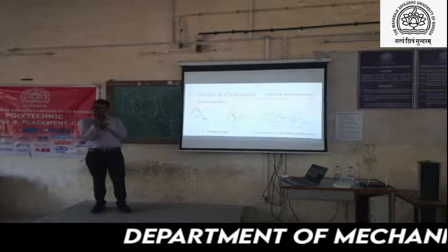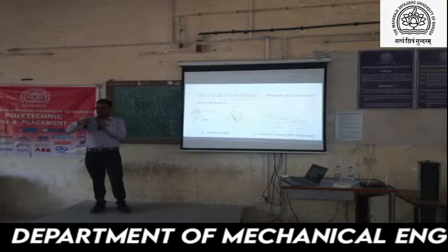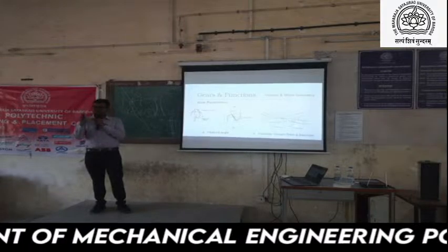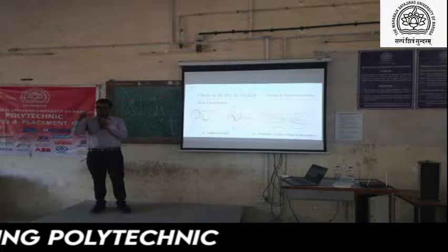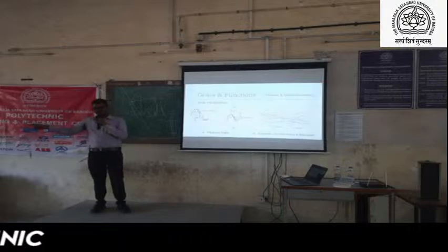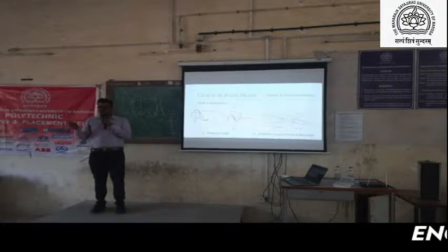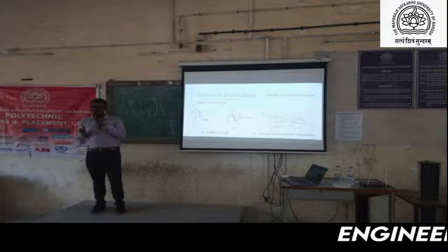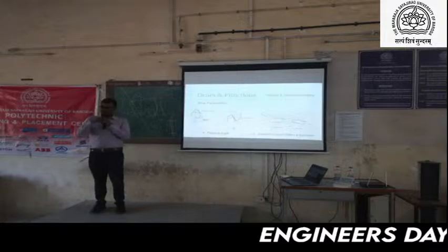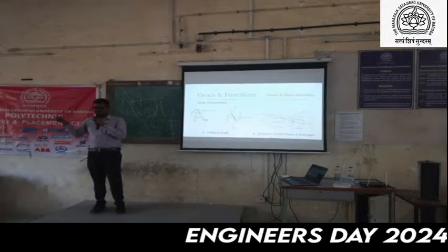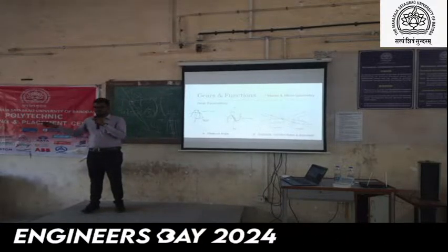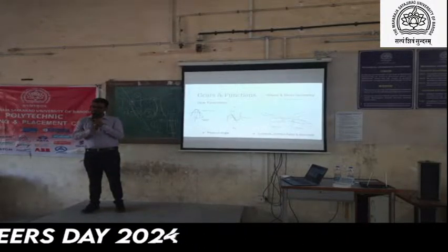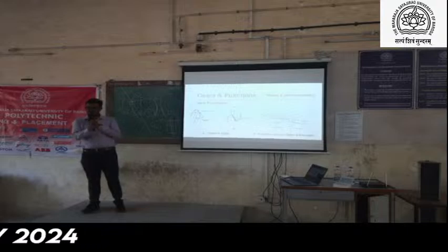So that tilt increases your contact, and that tilt is considered as overlap. So transverse contact ratio plus overlap ratio is the total contact ratio. Can you get my point? So in spur, the overlap ratio will be 0, so the total contact ratio is the transverse contact ratio. In helical, it will have some value.